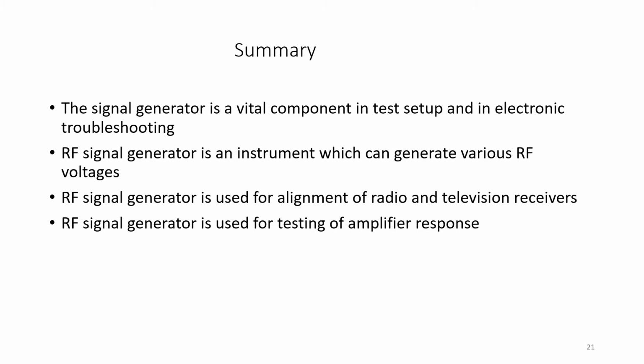So as I told you, a signal generator basically is a vital component in a test setup and in electronic troubleshooting and development, whether on a service bench or in a research laboratory. These signal generators have a variety of applications such as checking the stage gain, the frequency response, and alignment in receivers, and in a wide range of electronic equipment. They provide a variety of waveforms for testing electronic circuits, usually at low powers.